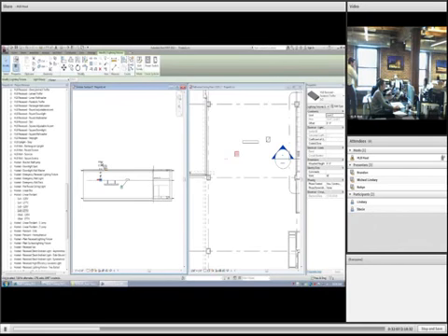I wouldn't say it's horribly clear. No. And in some ways, it demands the user knows what they're locking to. One issue with locking to these ceilings that we should be cautious about is that locking is error prone. Remember I said yesterday, locking dimensions and things like that, use it sparingly. We should, just because it is error prone to a degree.